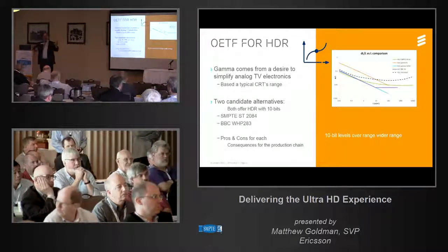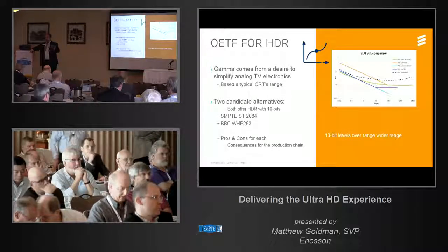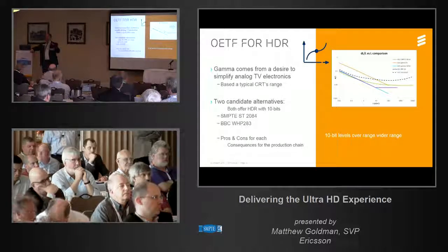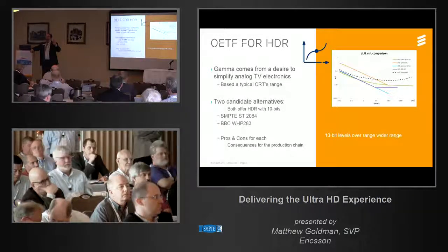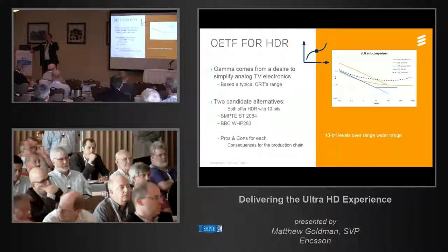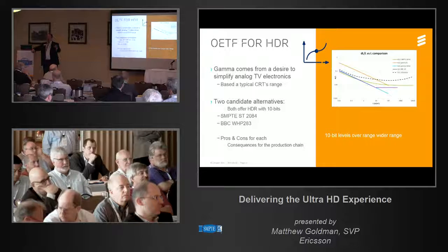In a television signal, not only is it digital, which means all the numbers that were analog are in digital, but there are actually 3 digital signals that are used. I know you think it would be RGB, but it's actually not. It's a luminance signal, or a level of brightness, which is Y, and there are a bunch of different color systems, but it's 2 color difference signals, whether it's UV or CrCb or PrPb.